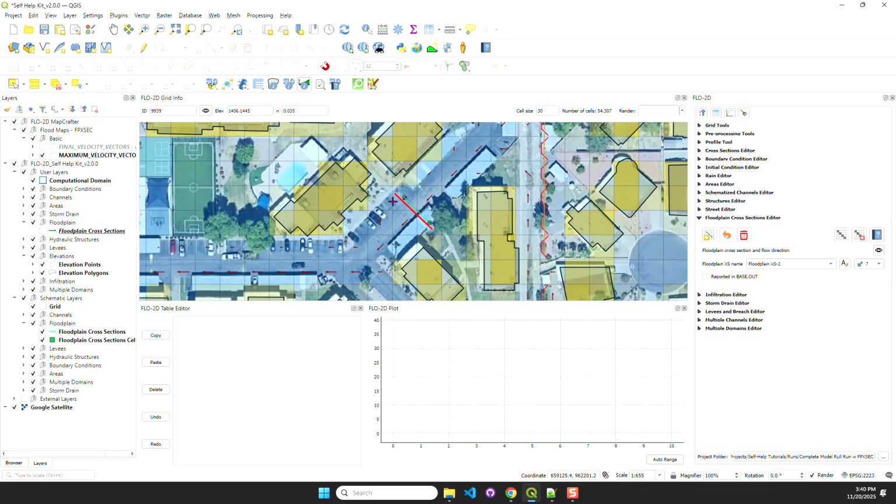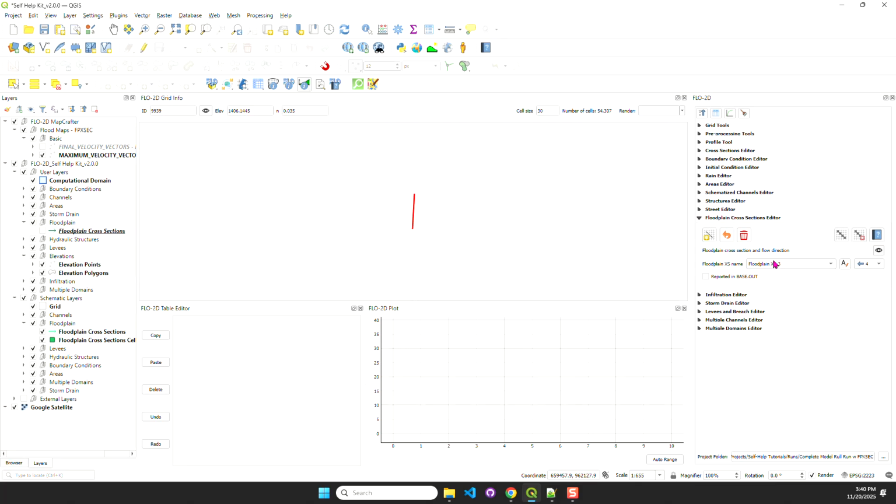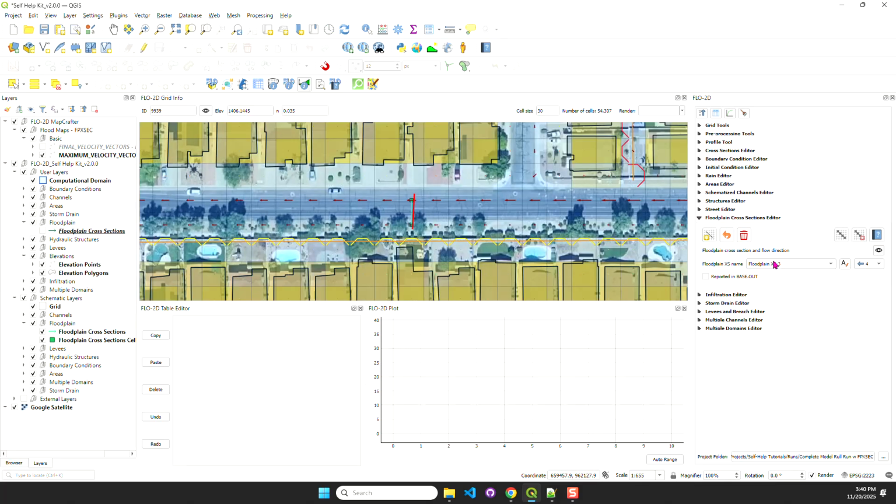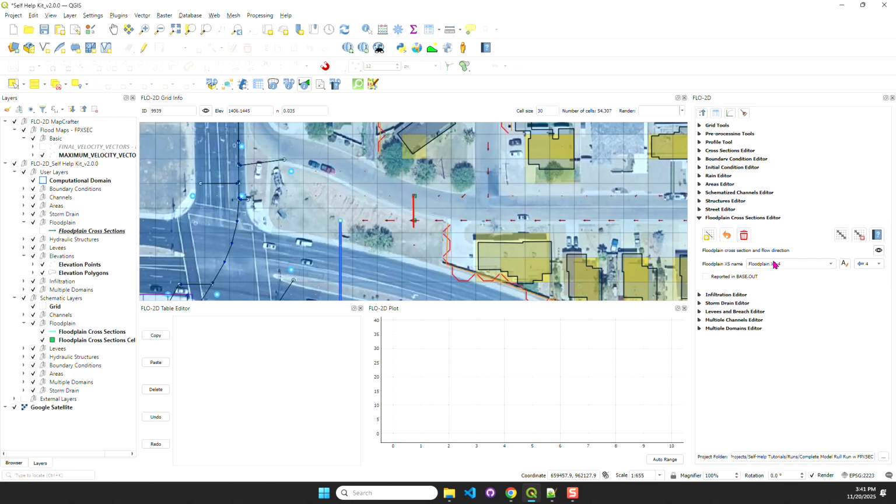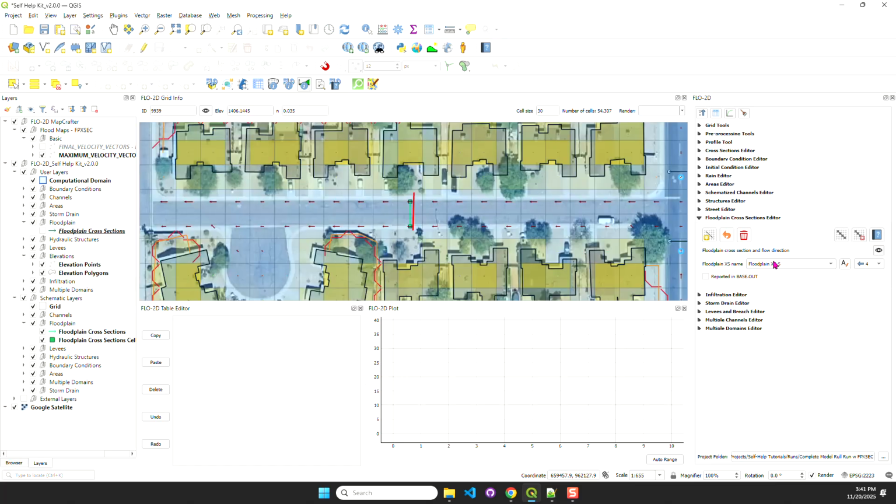And if it is diagonal like this, you can see here that your only two options are flow against the cross section. If you accidentally selected the wrong value, the reported flow would be a negative value. It would be a negative discharge, a negative velocity, and that's how it would be reported. You can see that that one is set up correctly. That one is okay. That one is set up correctly.